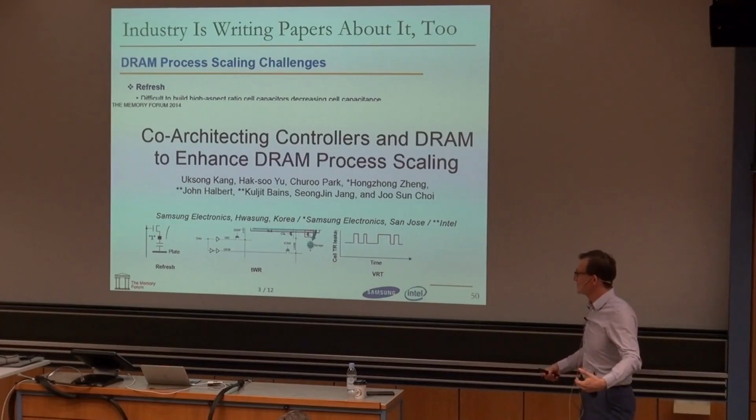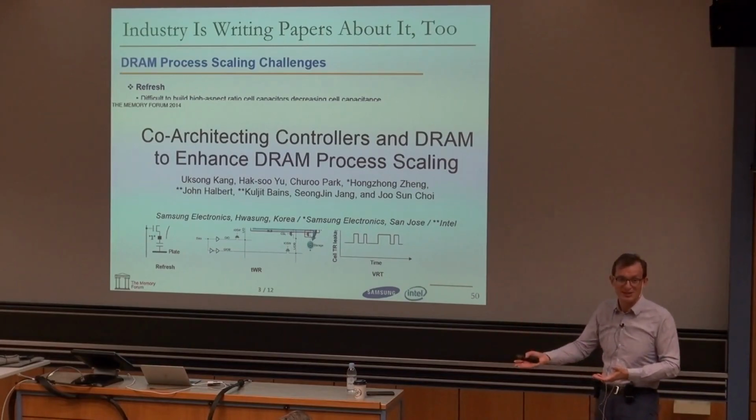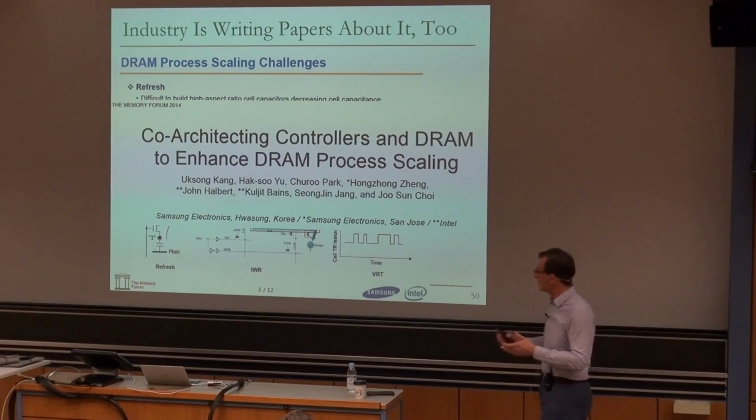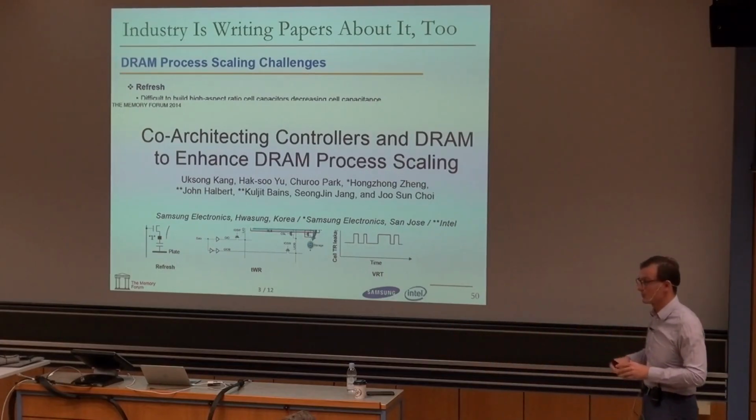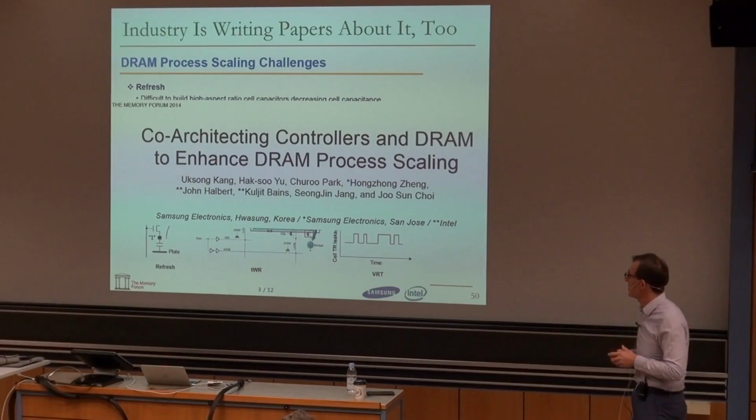That's one of the reasons capacity is not going to improve as fast, because you're going to use some of that capacity for something else to correct errors. And this is already happening. Mobile memories have error correcting codes going forward, and I believe all of the memories will have error correcting codes if they're beyond some capacity.